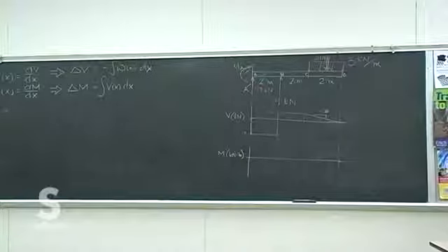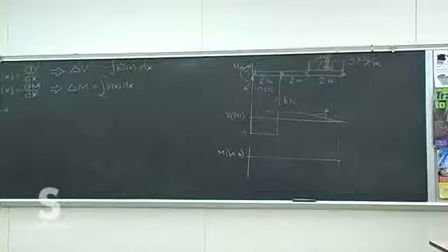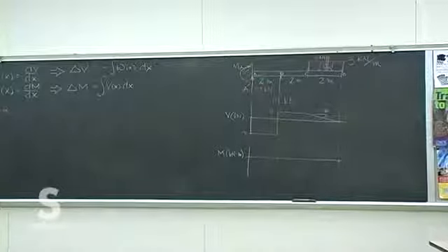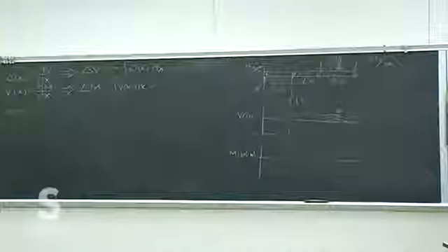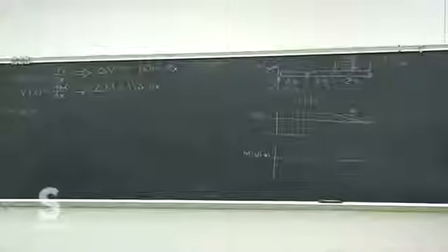You're covering it. Let me see it. No applied moments, so there's no jumps in the moment curve anywhere. There's breaks in the slope, discontinuities in the slope, but not any discontinuities in the curve, the line itself. There's no applied moments.